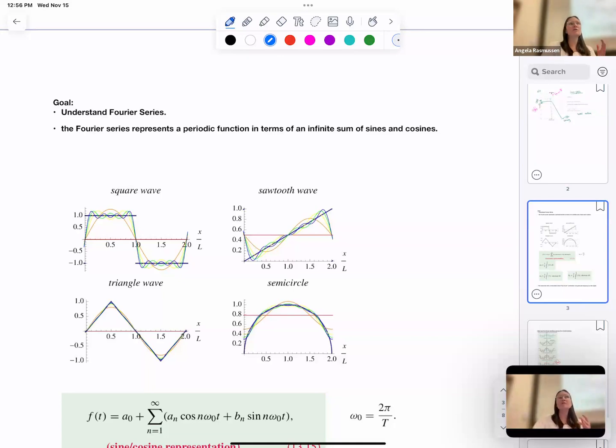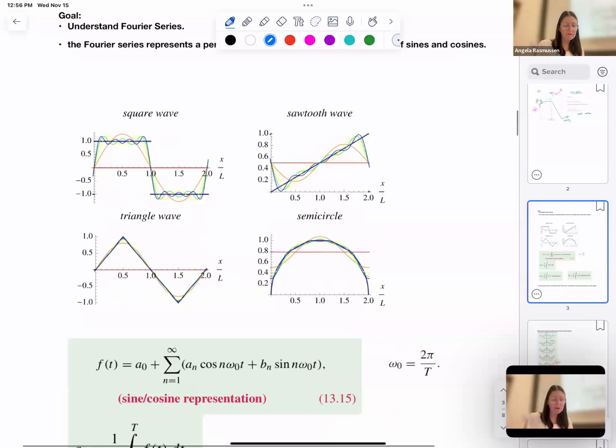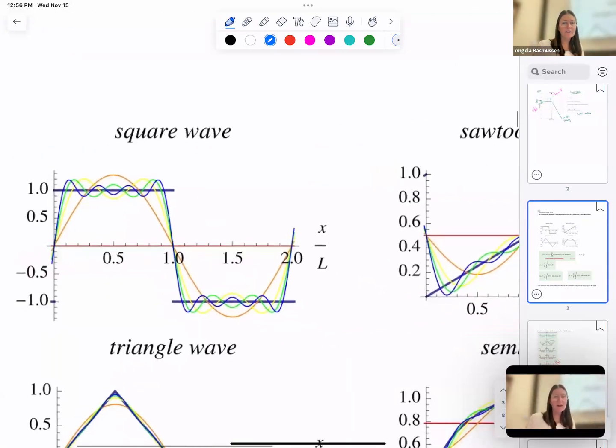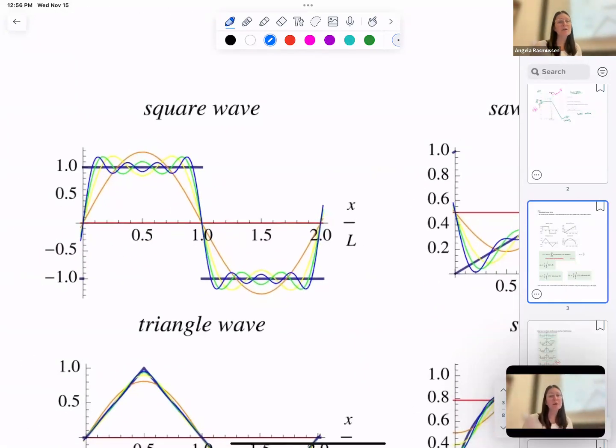So now this gives you a really powerful thing, that you can represent any signal, doesn't matter what it is, in terms of all these cosines and sines. A square wave that is represented as a sum of Fourier series looks like this, where it has a whole bunch of combinations of sinusoids in there, and it then looks like a square wave.